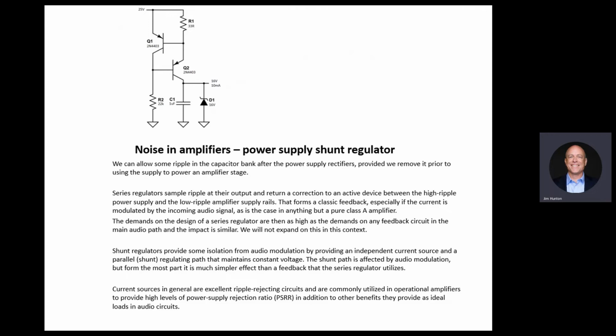So power supplies in audio amplifiers and audio equipment are audio devices. They're not DC power devices only. Don't ignore them and say this is easy. The designer needs to know that. And there are a lot of designers that take it for granted. Like, power supply, I'll just slap in some commercial power supply and I'm done. No. What are the characteristics of that supply? So you need to check that.